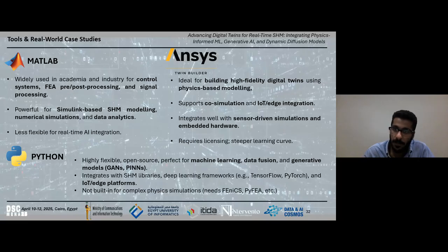You could have a prediction in real time once you have availability of the data from sensors, predict the location, and then go back to the fast analysis to identify the severity of the damage, for example, what's the percentage loss in the stiffness, what is the crack length, and what's the crack propagation rate on a concrete column. On the other hand, ANSYS Twin Builder supports real-time co-simulation, as you saw in the video, and connects to the live sensor feed.